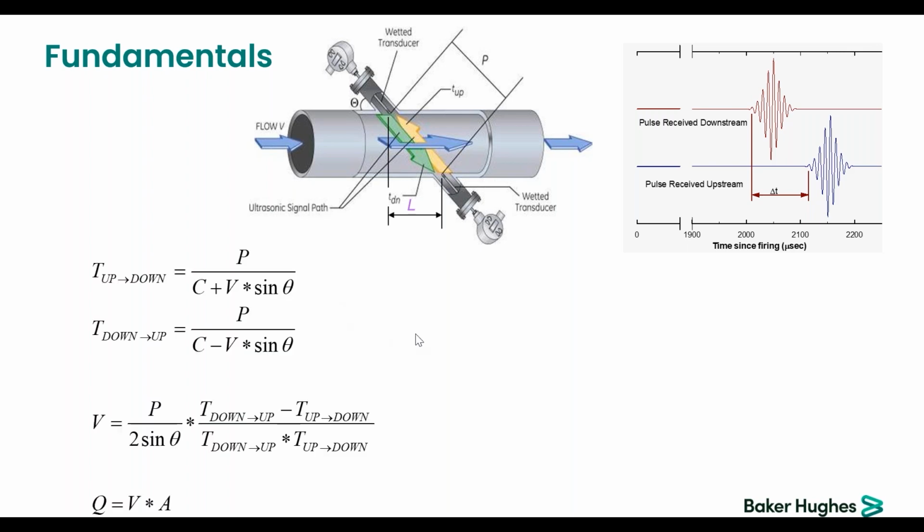And this is directly proportional, so there's nothing very complex about it. Now, if we look at what is important to know and what is measured, the velocity has to do with the distance between the probes, as well as the angle of the installation; all the rest is a matter of time.